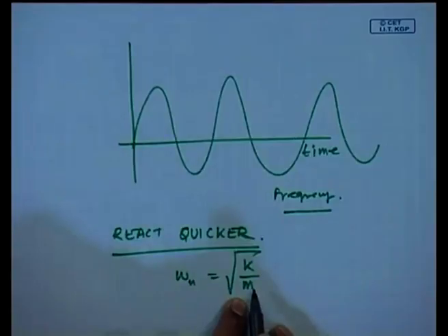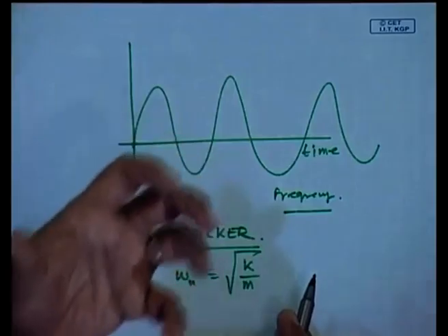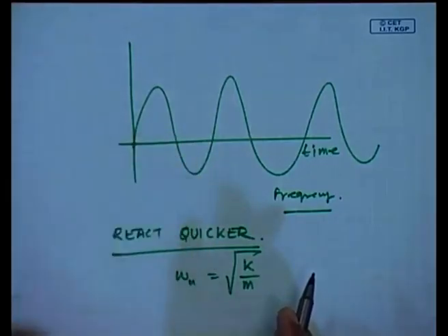Okay. So, that is why jockeys are of lesser weight. By the same token, if my mass is very heavy, the transducers will have a very poor frequency response. They cannot react faster. You would have cracked jokes with persons who are overweight. They have a poor reaction time because of this. Similarly, transducers which are heavy and bulky cannot respond fast to the mechanical parameters which they are sensing.